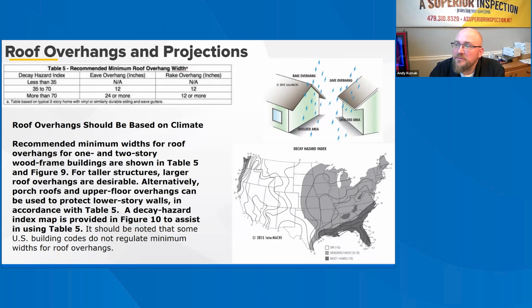Roof overhangs offer limited benefit during periods of severe wind-driven rain conditions, such as thunderstorm fronts and tropical storms, and in arid regions where rain is not a major concern. In severe wind-driven rain climates, a good performing weather-resistant barrier for walls is at least as important as providing roof overhangs. In high wind areas, overhangs add wind uplift load to the roof and may require stronger roof-to-wall connections.